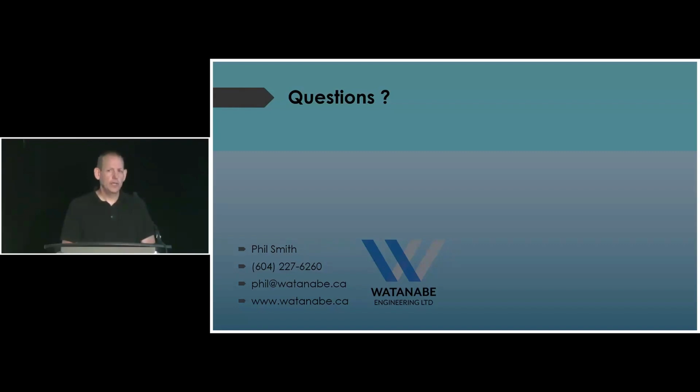Okay, yeah. Some of the transmitters are a little different. The one that we use is generally all built into one transmitter, with the antenna on the bottom of it, all in the same unit. But if you're starting to get issues with those, I would go back to the manufacturer and take a look, because you can get into more specialized applications with radar. Again, the cost might be prohibitive, depending on your application. But you can put different radar antennas on the bottom of them, the big cone ones, and they can start tuning out some of that kind of false frequency stuff.